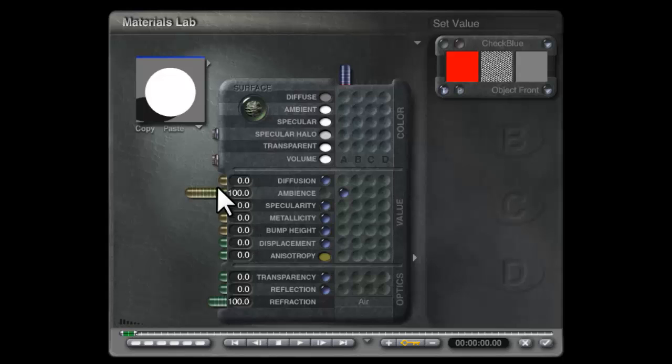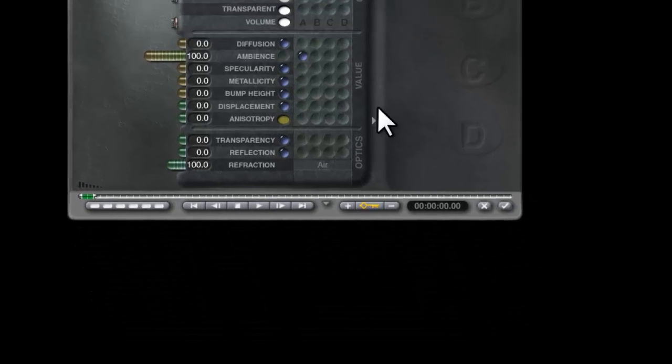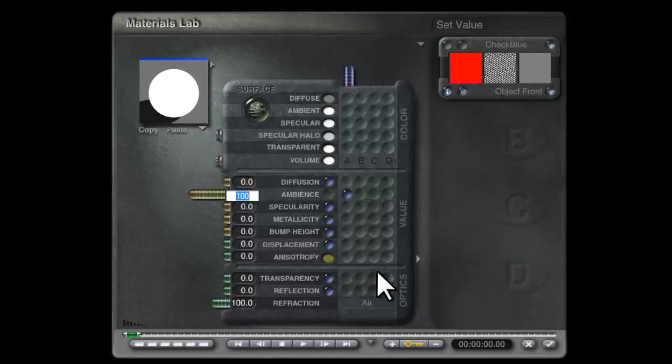If I check out of here now, you see the ambient output suddenly boosted to the point where it's looking fully white. And that's what I was looking for. So this output now is extremely high. So high in fact that I'll probably have to use alpha scaling for the first stages of this and set it down to a low level. So let's try 0.1 there.